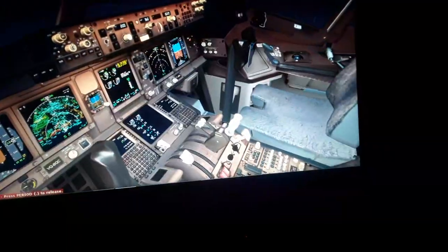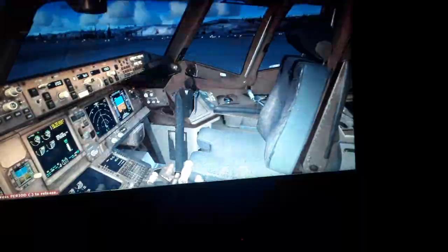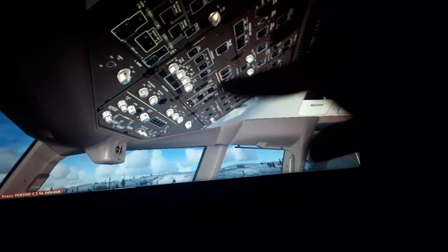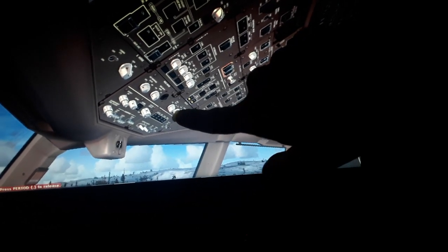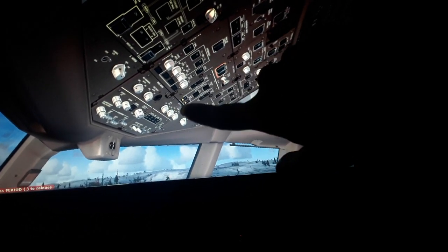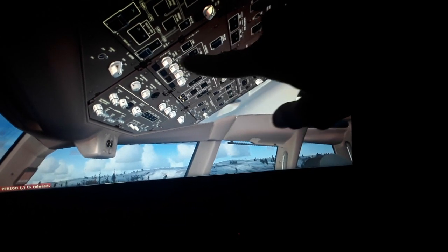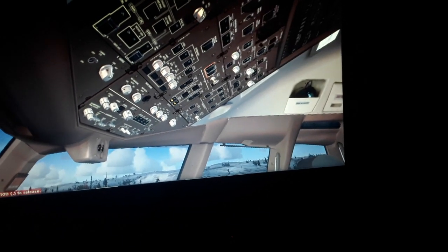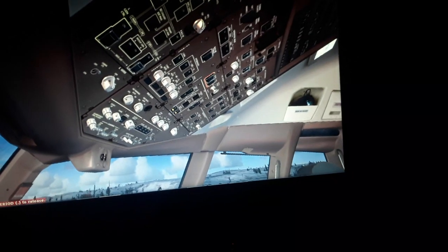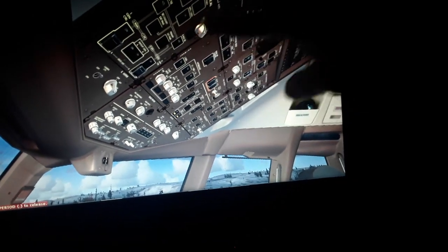to start the engines on the ground. So I'm gonna show you how to do all these things. We also need cabin pressurization, wing and engine anti-ice over here, hydraulic fluid pressurization, air conditioning and ventilation, and start the engines using the APU, the auxiliary power unit. So this will provide hydraulic power on the ground. So I'm gonna show you now